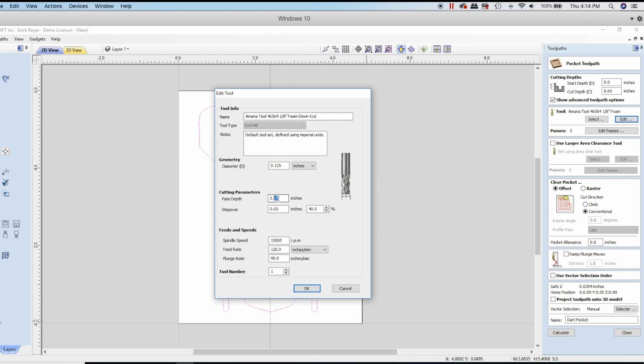But in foam, because it's a very low load material, and it's really soft, the end mill is going to move through nicely. I'm comfortable with going 2 times. I can go more than that. I could probably cut this entire thing in one pass, but what I'm concerned about are the small little peels that you get, the equivalent of chips with foam.